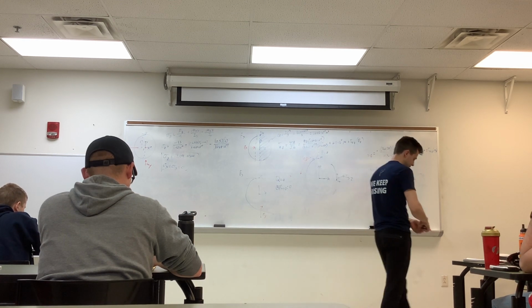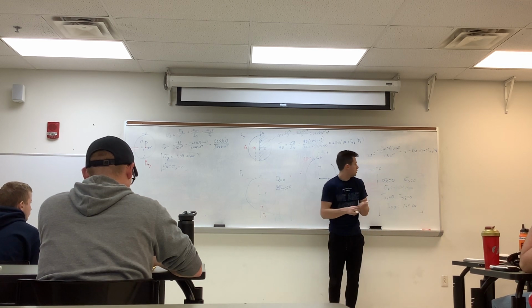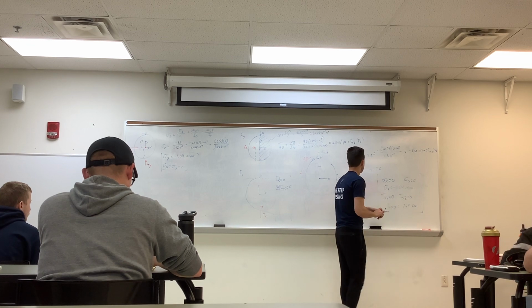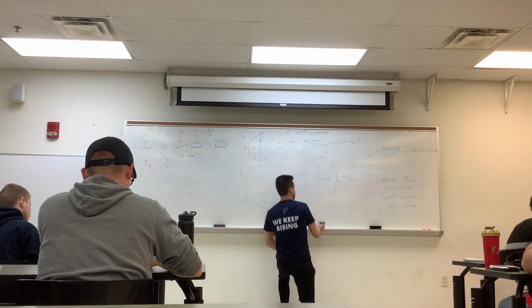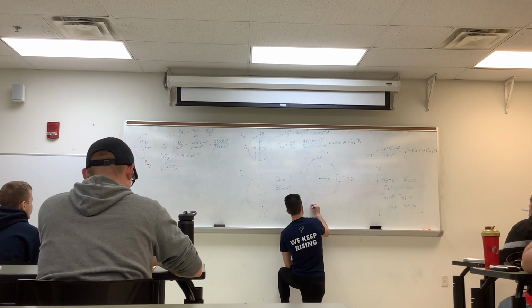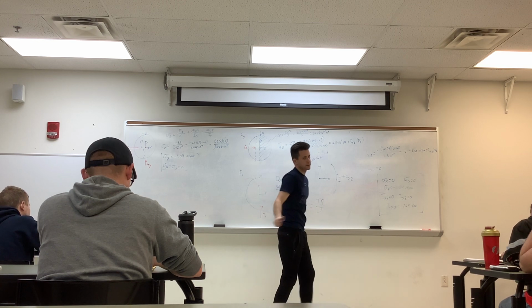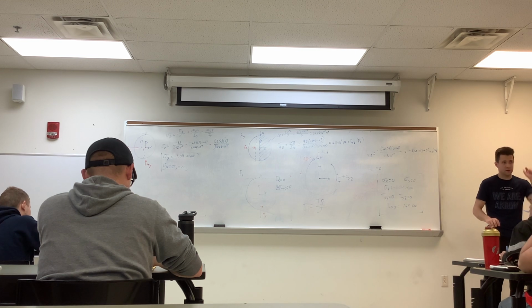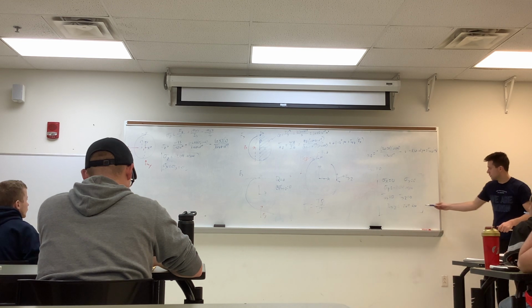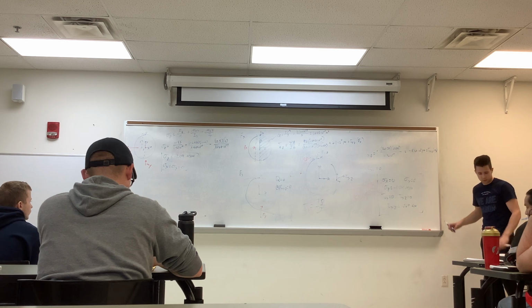What is the equation you used for tau xz? I'll give it to you, the torsional moment. It's T rho over J. Okay, that's that equation. You said for tau xz, when you use software, what all do you add up? How did you get negative 76.4 kilopascal?